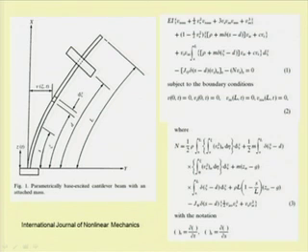So, this is the system. In this case this is a slender beam carrying a lumped mass in which the base is excited. The base excitation Z(t) can be written as Z 0 sin omega t, so this is a harmonically excited base. This is a cantilever beam excited harmonically, and as the beam is excited harmonically, the governing equation of motion, of which one can find the detail in that paper, can be written in this form.